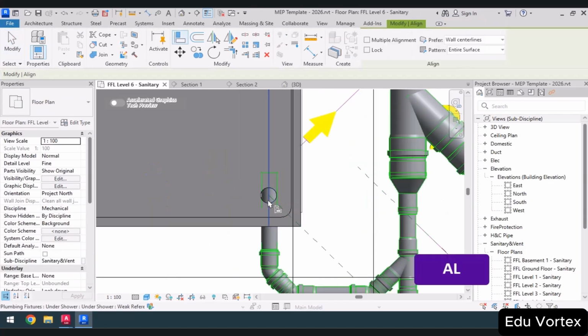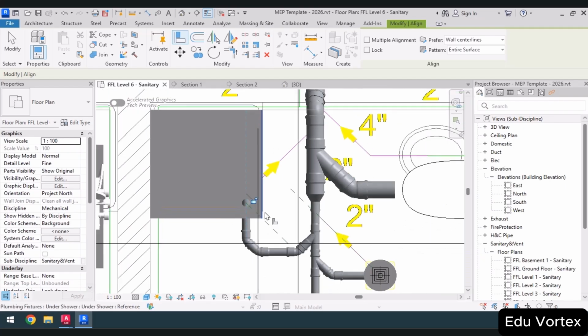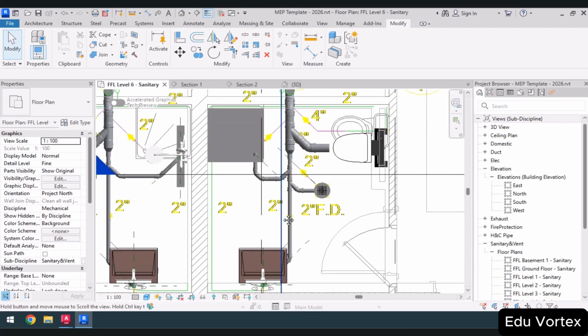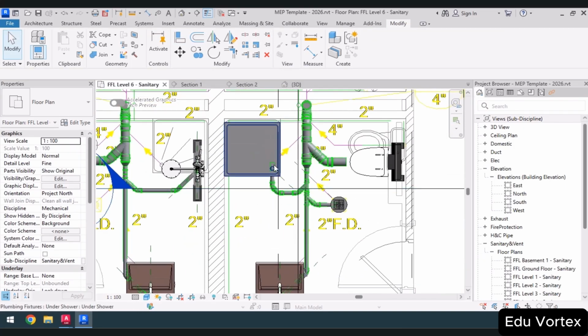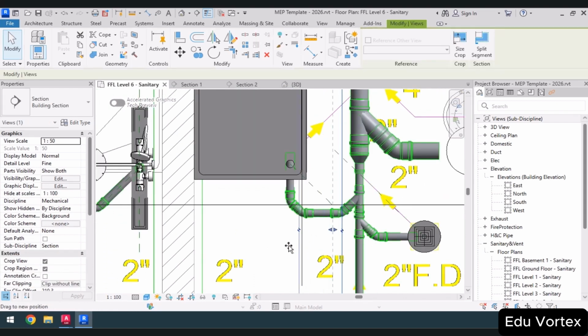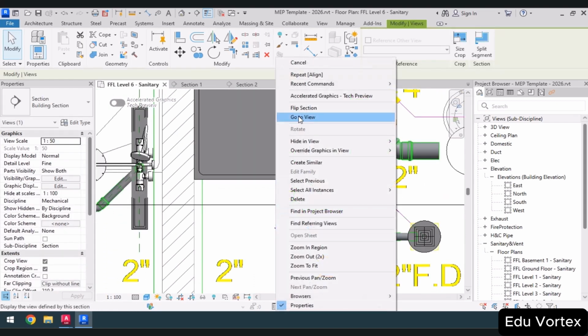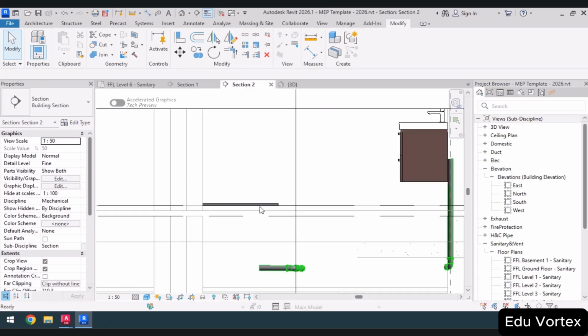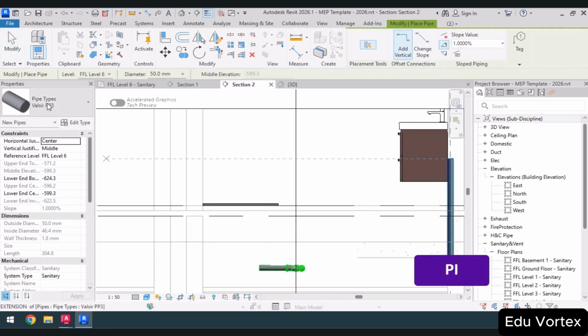Now aligning this connection with this pipe should be done correctly. Then the first item I need to check is whether it fits well in this area. So it seems that the siphon might not fit in this section. I right click and go to the view, use the pipe command PI to check 5 items related to the connection, system type and size.